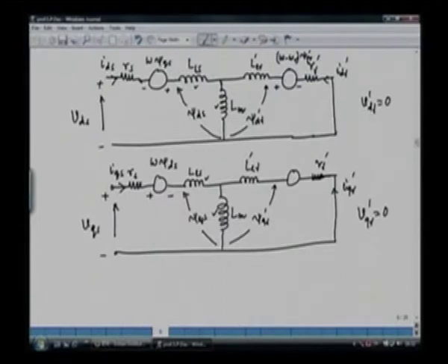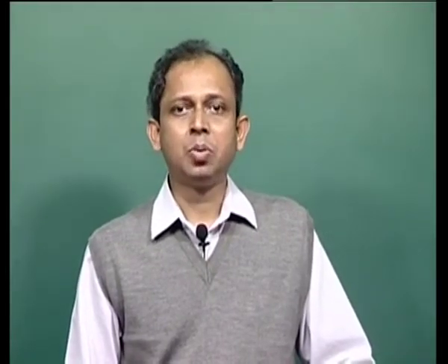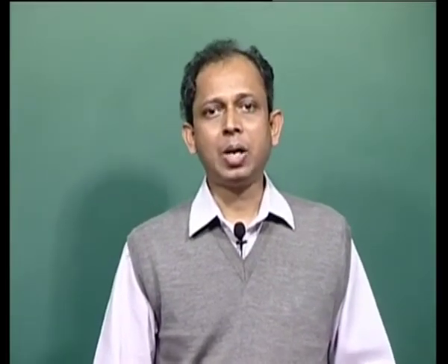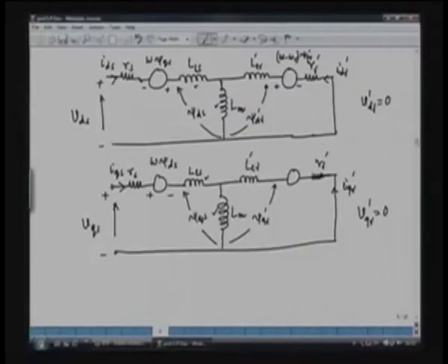So this is the equivalent circuit of an induction machine in arbitrary reference frame, and if we take this equivalent circuit, we can simulate the machine both in the transient condition, also in the steady state condition, without any loss of accuracy. And we can get back the original currents IA, IB and IC when we transform IDS, IQS and IOS by means of the transformation matrix into IA, IB and IC. So this finishes the modeling of the induction machine.